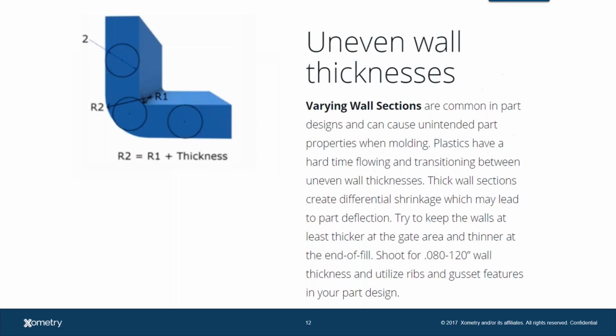The next thing I want to talk about is keeping an even wall thickness. When you're CNC machining, you're looking at more is less, where you're removing from a block, and anything that you don't remove is time saved. With other processes, less is more. In 3D printing, we talk about the complexity paradox, where you can actually add complexity without necessarily adding cost.